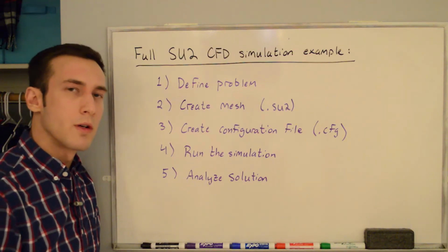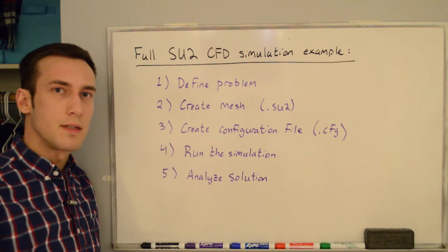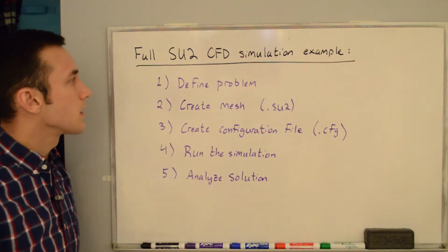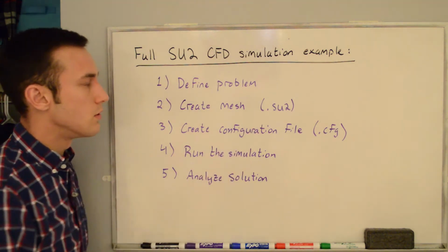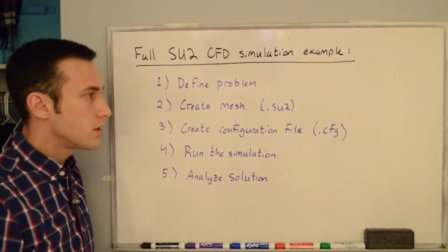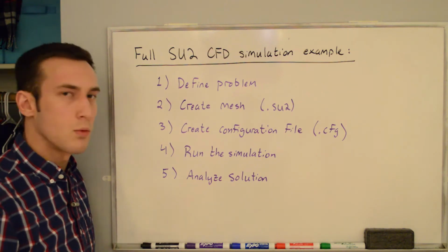Hey everyone, in this video we're going to be going through a full example from start to finish for how to run a CFD simulation in SU2. So the steps that we're going to take are first to define the problem, second to create the mesh, which is the .su2 file, third create the configuration file, which is the .cfg file, fourth run the simulation, and then fifth we'll analyze the solution.